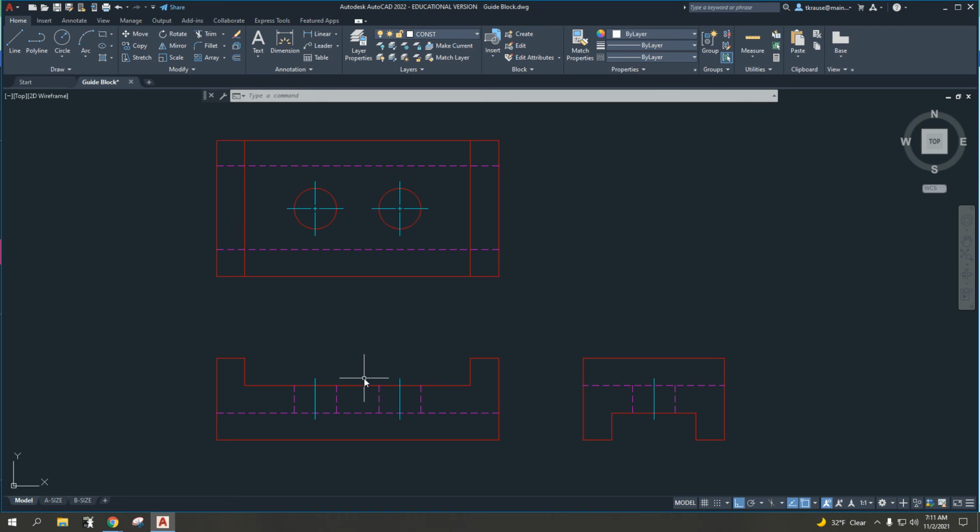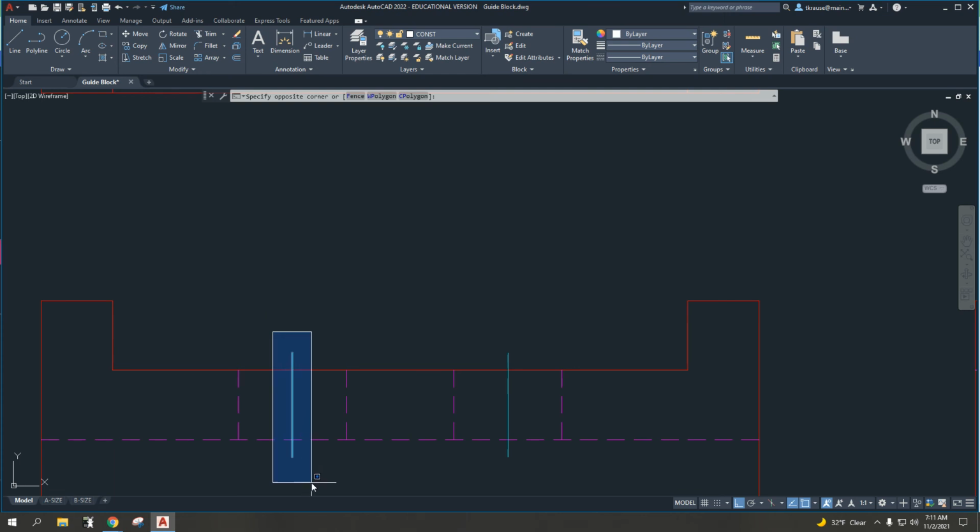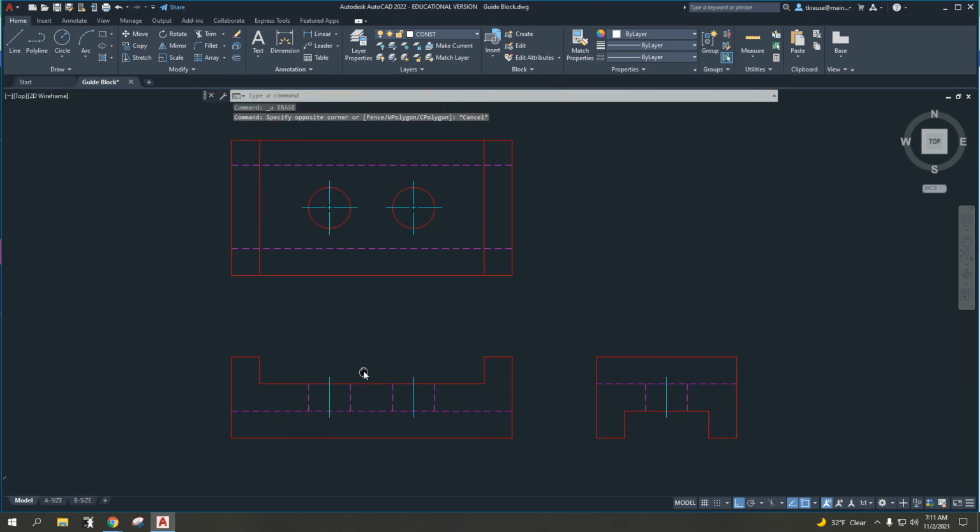Now the big new thing in this particular file is that on this drawing, we don't see the dashes for the center marks. We can see small center marks here in the circle, and we need to change some things. Depending upon the object you're drawing, sometimes there are dashes for hidden lines or center marks, and they might not be the size that we need them to be.